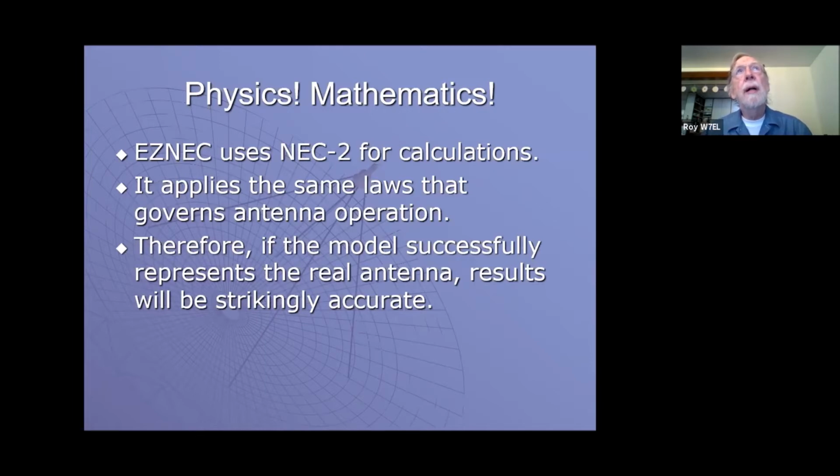And in my models, I have accounted for various bends and so forth, and the dipoles have pretty broad patterns. So I have quite good confidence in the patterns that I see for those. But there are a lot of cases where it's virtually impossible to completely imitate the environment of an antenna. You can include things like rain gutters and so forth, but you have to know what size and position they are in order to tell the program, and a lot of times you don't know that.